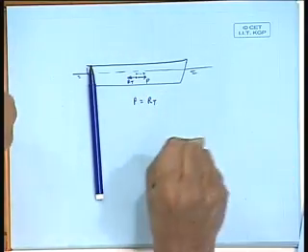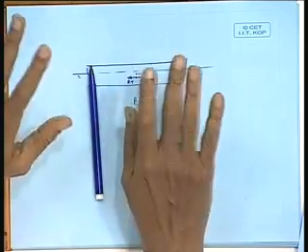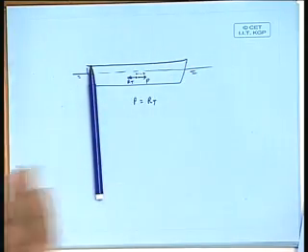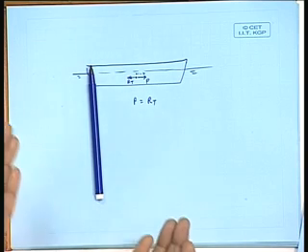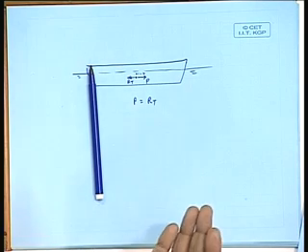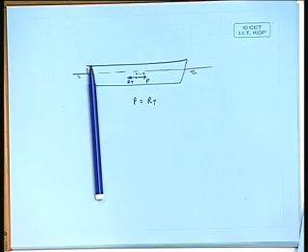I am not saying that it has to be done accurately, it can't be because we do not know. For example, if I am talking of planing craft towing resistance, the vessel actually comes up, it lifts itself. So, the bottom is more or less near the water surface. So, actually in that position my tow hook should be near, attached to the bottom of the ship, but I can't attach it to the bottom. There must be some distance between the bottom and the attachment point.